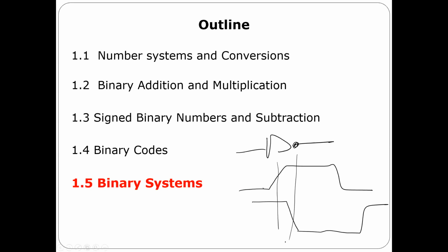Okay. The longer the delay here, the lower the input frequency I can use. What is the relation? By just common sense, it's very simple. I can't make the input change very quickly, shorter than this time, because the first one hasn't finished yet. It takes some time to flip the first one, so before it flips, I can't give you the second one.